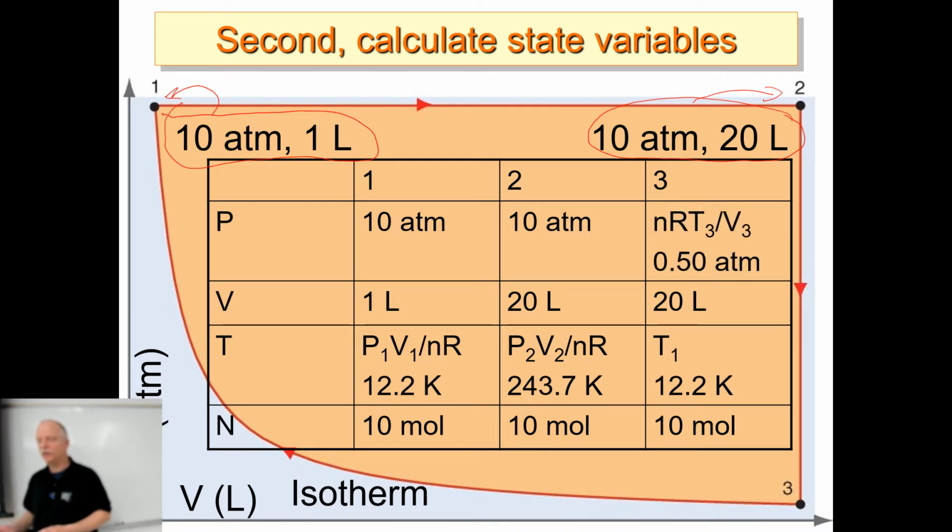And then we've got the temperature 3 and volume 3. We can solve for the pressure at point 3. So that pressure dropped quite a ways because we went from 240 Kelvin down to 12. So it really dropped. This really isn't a realistic cycle. I don't think we could operate a cycle like this at 12 Kelvin, but it is helium, so it's not going to condense just yet.